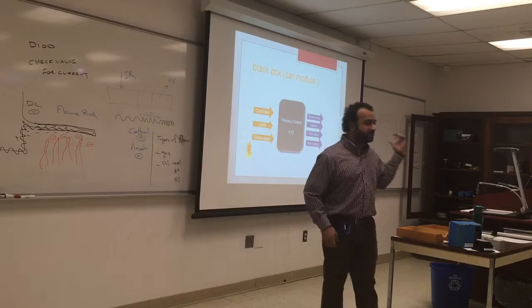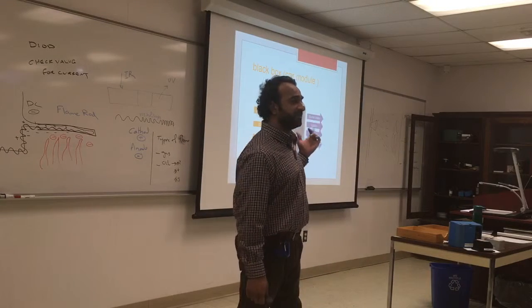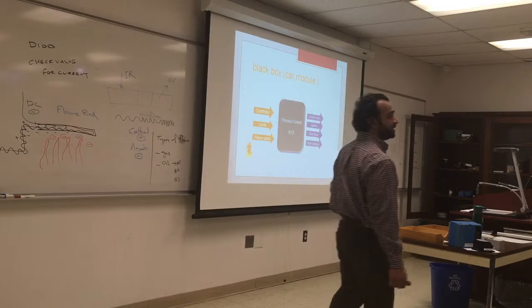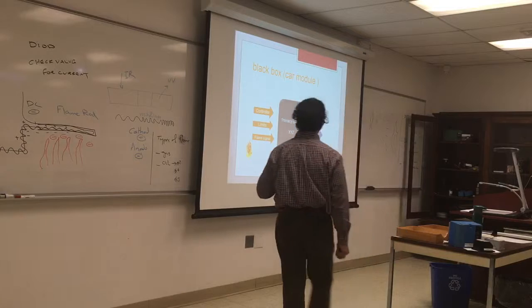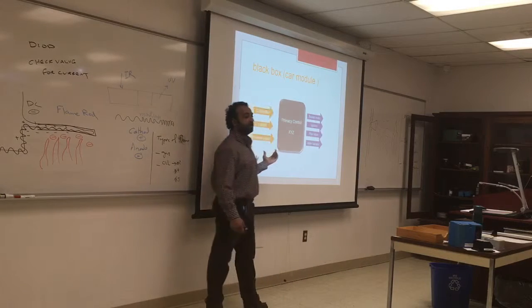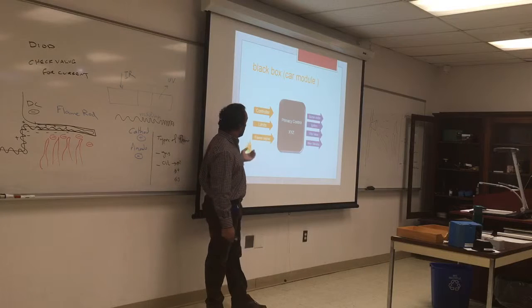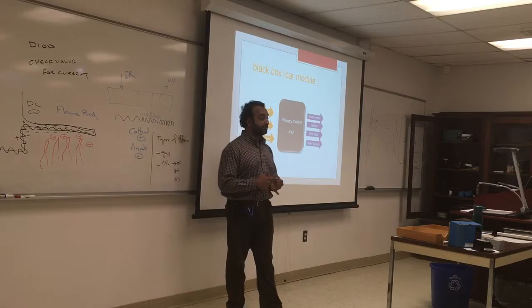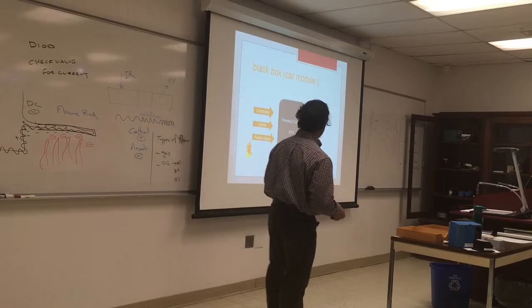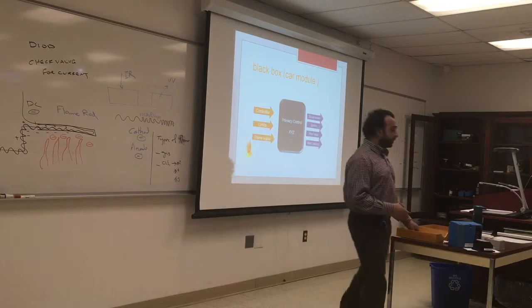So we treat the primary control as a black box. We do not disassemble or open it, and most of those controls are very expensive, and they don't want you to take it apart because it has very sensitive relays and very sensitive contacts, and some of them are airtight. They are sealed in vacuum, so they don't get air in them. And we check the inputs. Are we getting the right input from the air sensor, from the flow meter, from the flame, and we check the output based on the sequence of operation.